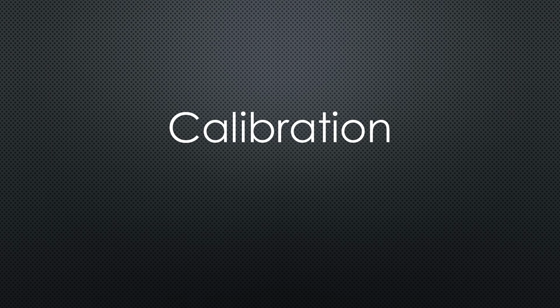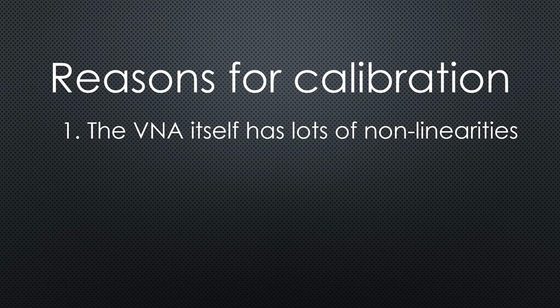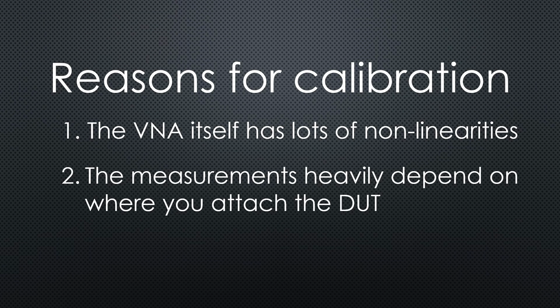The most important thing you have to know is calibration. Never use an uncalibrated VNA. Never. It will show wrong values and fool you. There are two reasons for calibration. One, the VNA itself has lots of non-linearities. And two, the measurements heavily depend on where you attach the DUT.